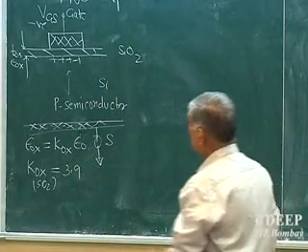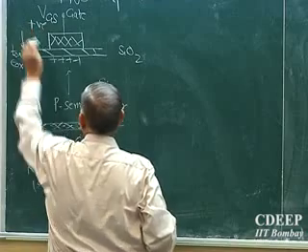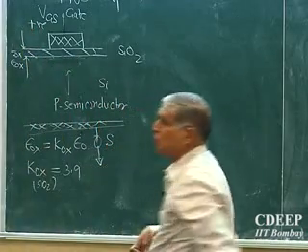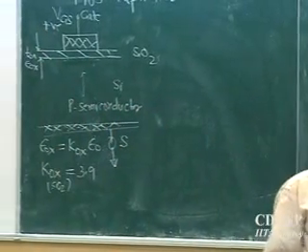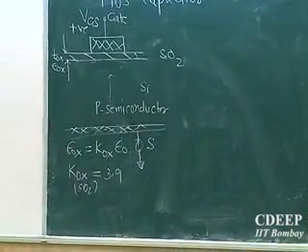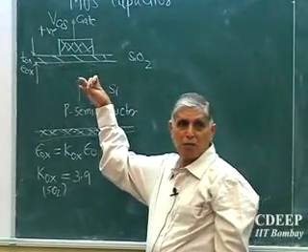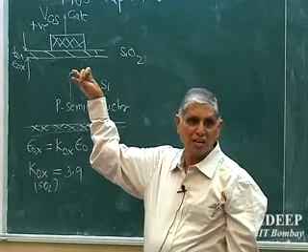If I apply plus voltage, as I said yesterday, since I am applying positive charge on the metal with reference to the semiconductor, I expect negative charges to appear below the surface of the silicon dioxide.